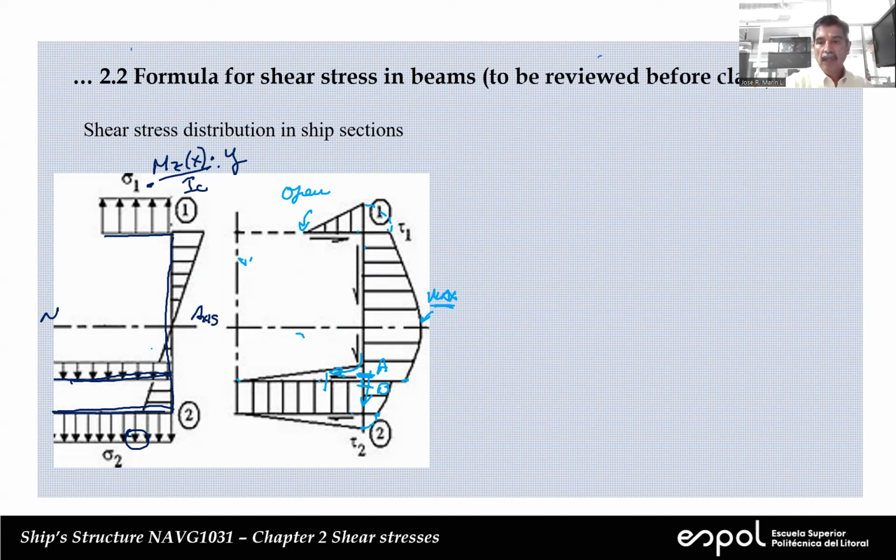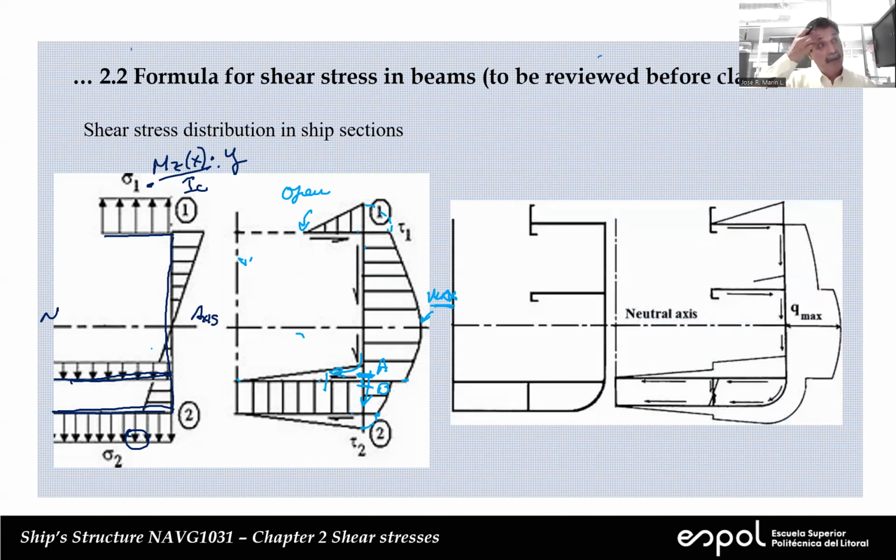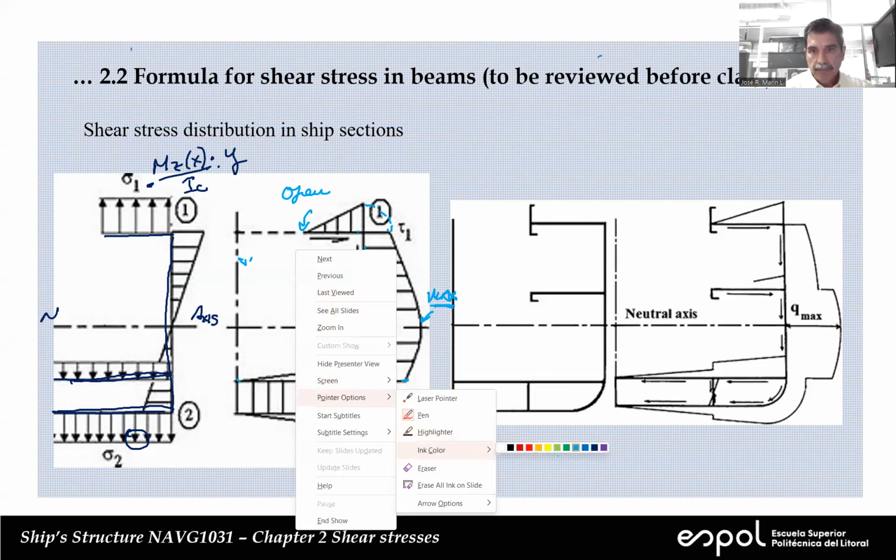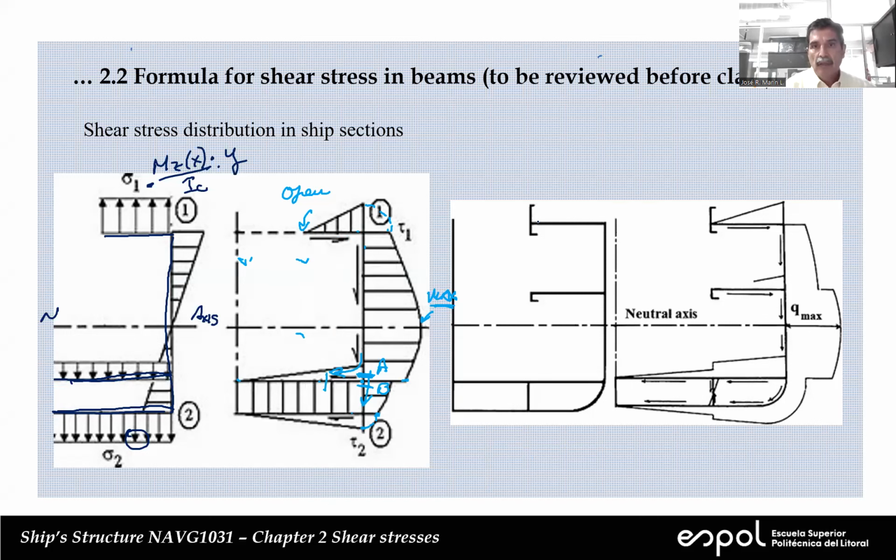No questions. Good. In here, we have something similar. This could be a large cargo vessel. You see that you have two decks, and both decks have openings. Again, we start here, which is open. We can neglect this reinforcement, and we can go and increase linearly on the deck. In this case, you are not considering tau, you are considering the shear flow.